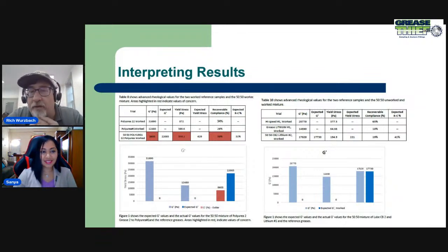But what we're showing here is the rheological properties of the grease. And more than just the cone penetration, which is like, how is it still a clump of grease that's going to stop a cone? These are the dynamic behavior measurements of the grease. How's it going to behave when a roller is going over it trying to make that film?